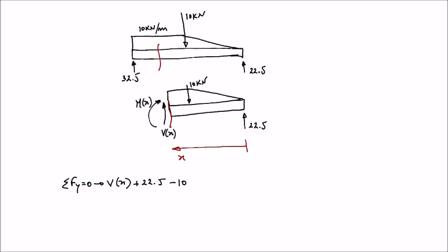We didn't have this in the previous page, when we cut the beam previously, but we have it now, when we cut the beam between point A and the midpoint of the beam, and when we look at the right side, we need to consider now the concentrated load at the midpoint of the beam.